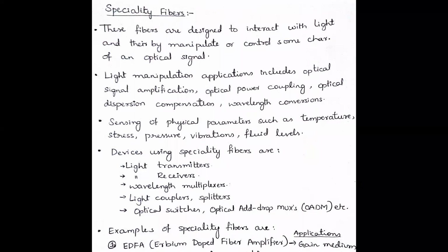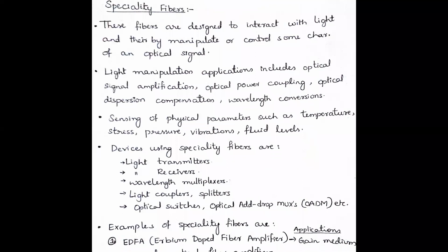So, devices which are using specialty fibers, I think I've answered the question which has been asked. So you can just go through the screen. Devices using specialty fibers are light transmitters, receivers, wavelength multiplexers, demultiplexers, couplers, splitters, and optical add-drop multiplexers. So these are some of the devices which make use of specialty fibers, as we discussed earlier, that is PCF, photonic crystal fiber, index guided, as well as band gap fibers.